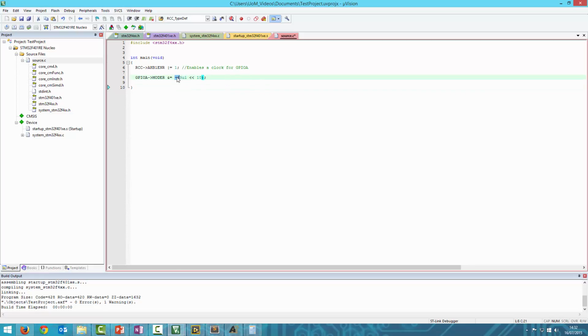because that's going to NOT this value, because what we did there was we shifted 3 across 10 places, and everything else was going to be 0, but this will make 0 0 shifted across 10 places, but everything else be 1, which is what we want to do. We only want to blank 2 numbers off. I know it looks confusing, but you will get the hang of it. And then, so we've not actually set anything there. We've just blanked the 2 configuration bits.